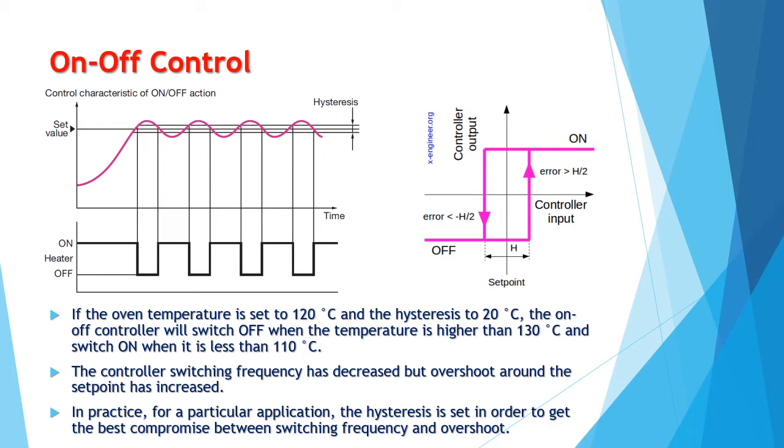In practice, for a particular application, the hysteresis is set in order to get the best compromise between switching frequency and overshoot.